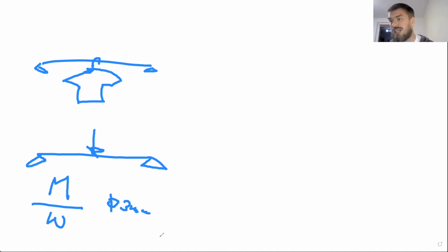And yet, somehow, miraculously, we don't do titanium laundry strings, right? It's a normal nylon thing that can withstand maybe 3 megapascals of stress. So how is it that it didn't fail? And to imagine why it wouldn't fail, I will do an experiment that's very simple. Normally, you don't draw static schematics like this. You would instantly add a sliding support on one end to make it statically determined, right? That would be the approach civil engineering teaches instantly.